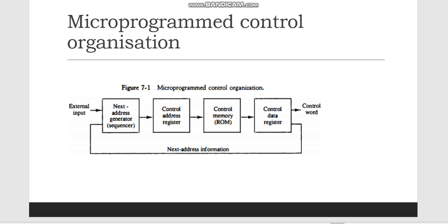Since alterations of the microprogram are not needed once the control unit is in operation, the control memory can be a read-only memory, ROM. The content of the words in ROM are fixed and cannot be altered by simple programming, since no writing capability is available in the ROM. ROM words are made permanent during the hardware production of the unit. The use of a microprogram involves placing all control variables in words of ROM for use by the control unit through successive read operations. The content of the word in ROM at a given address specifies a micro-instruction.